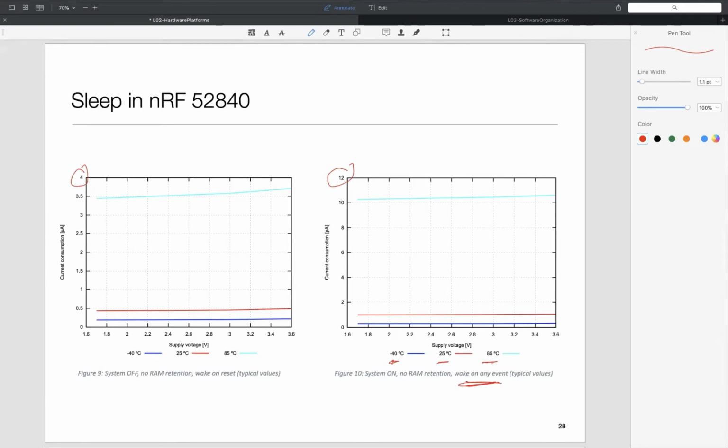And this can actually lead to some interesting things. As you burn power, if you don't remove the heat which is coming out, then that heat is going to remain trapped in the package and is going to increase the temperature of the electronics more, and the electronics will consume more power, and the temperature will go up even more, and you end up in a kind of thermal runaway, okay? So it's very important that the hardware side of the design team should design things so that the heat is removed. Otherwise, you run into essentially thermal runaway, the temperature will rise very high, and then either the system will shut down if you have so designed it, or worse yet, it can just destroy itself.